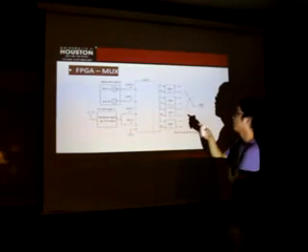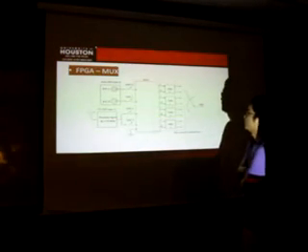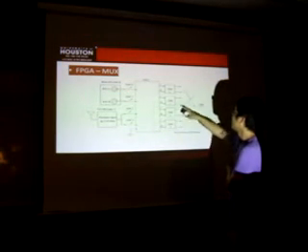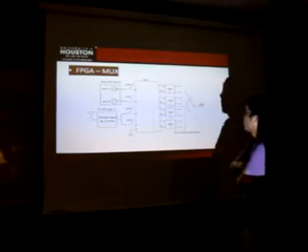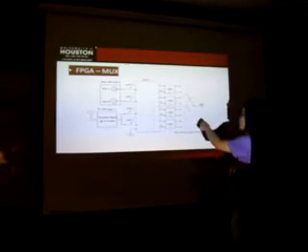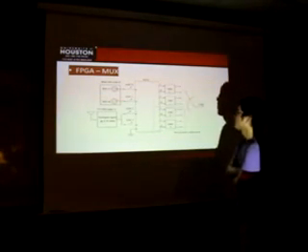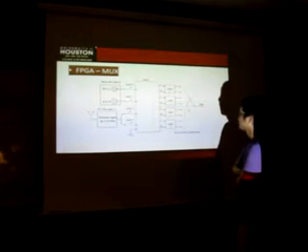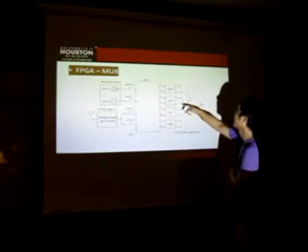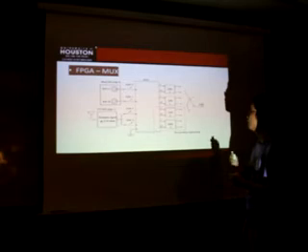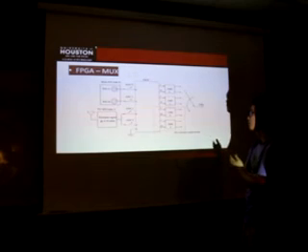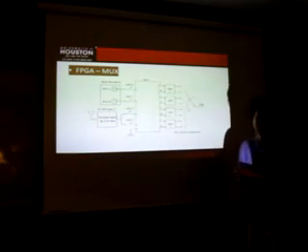Here is the FPGA part for USRP1. At the USRP1, the sampled signal goes through the DDC, because the data rate is too fast for the USB transmission. So there are some down-sampling converters here. They lower the data rate of the signal and send it to USB. Through the USB, the data is sent to the personal computer and processed.